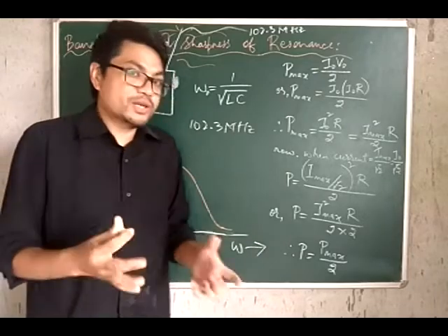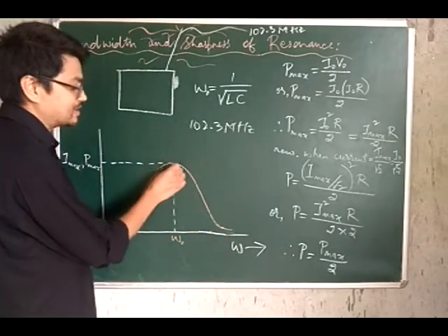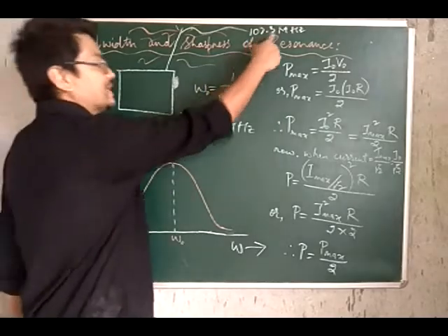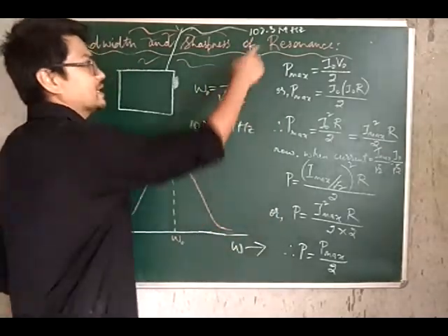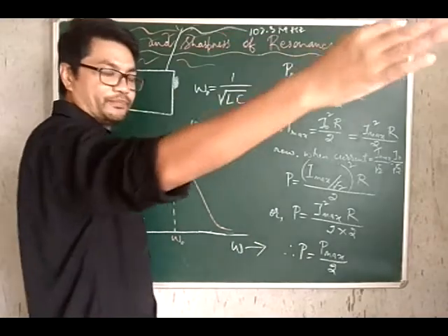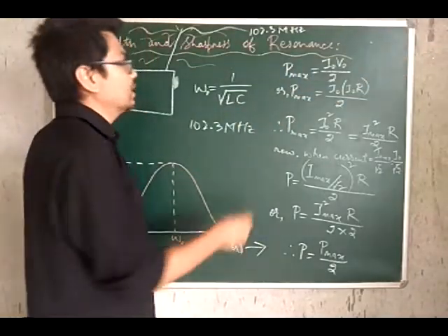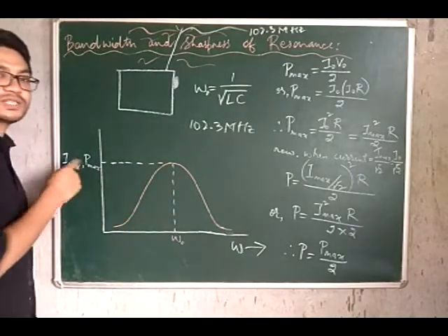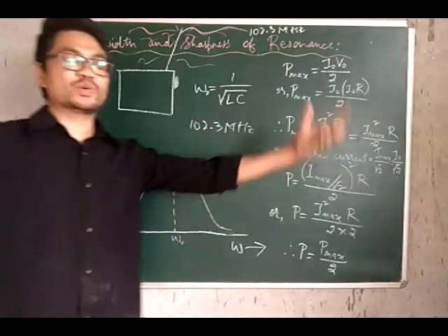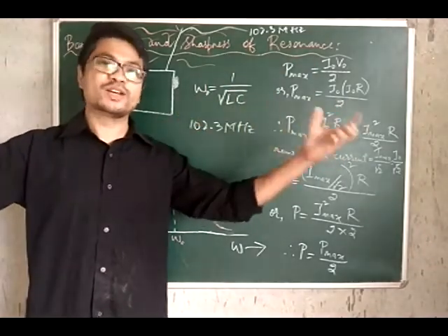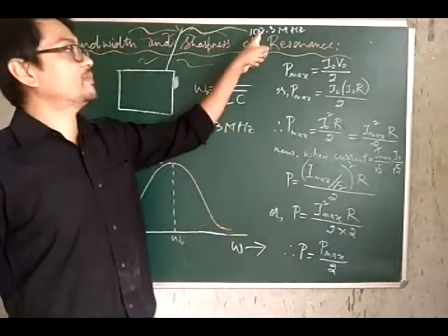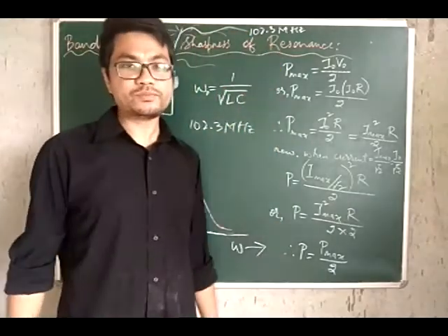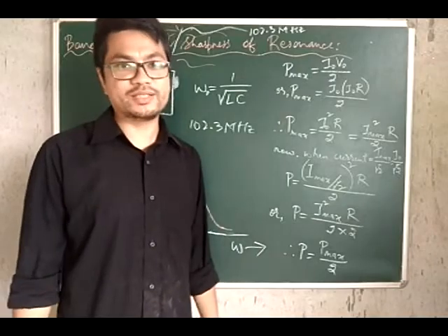And when they resonate, you get a nice, clear, distinct sound. Okay? Because when these two frequencies resonate, this frequency coming from the radio station in Kershon produces, so to say, the maximum value of current and the maximum value of power. So therefore you get a nice sound, or you get to listen to all of the information coming from the radio station corresponding to this frequency. So this is what happens in resonance.